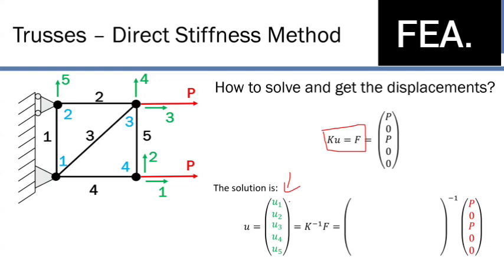Obviously, for different elements, it's somewhat different, but here it's a simple element with two nodes attached to it. Obviously, in FEA, you can have triangular elements, you can have quadrilateral elements. Those are obviously more complex, but as a very ground level principle, this is what's going on. You're generating a stiffness matrix, you're generating external loading, and you're mixing those two together to computationally determine the displacement. So that's the theoretical side of what's going on.